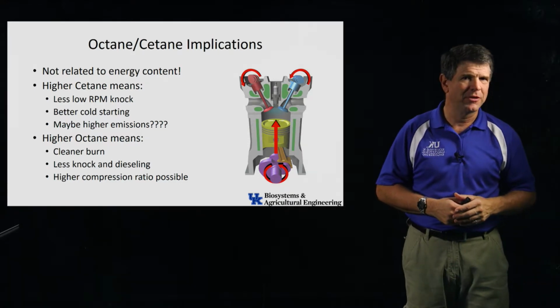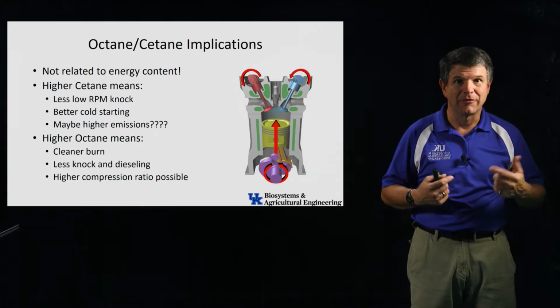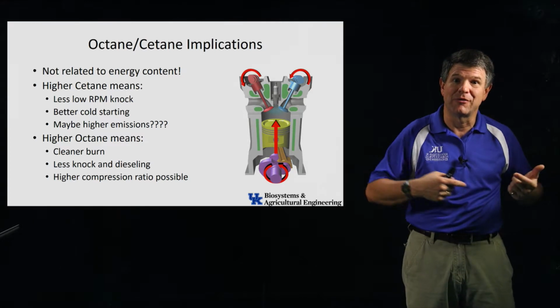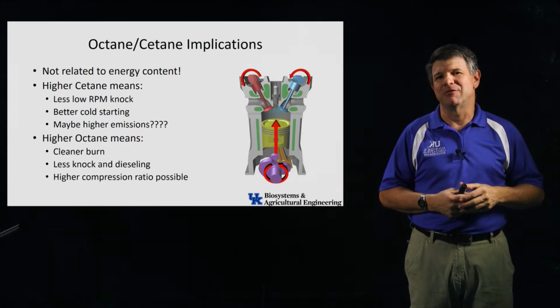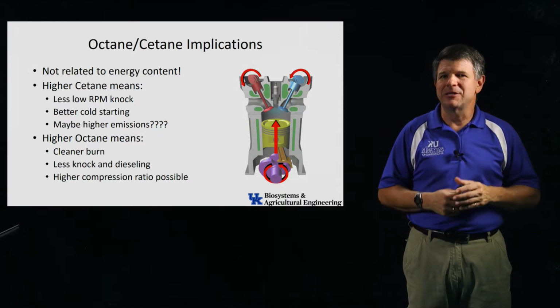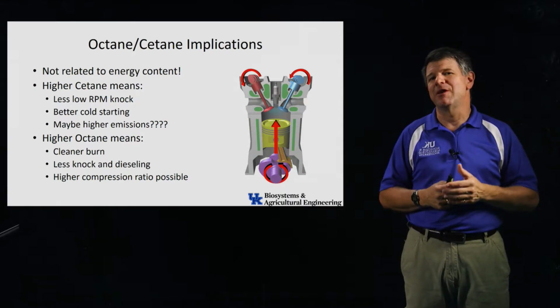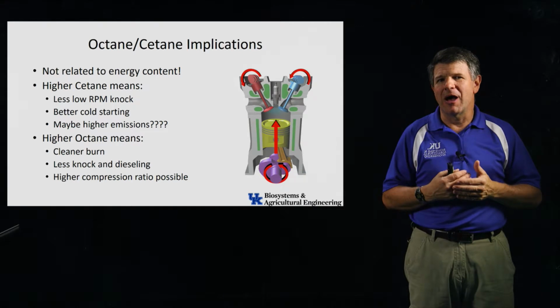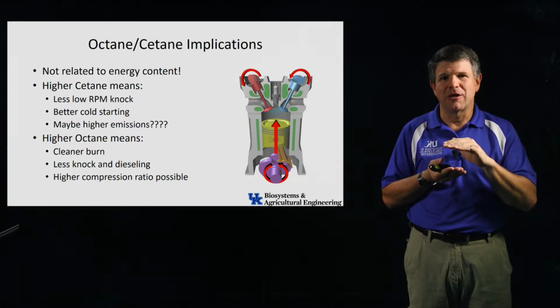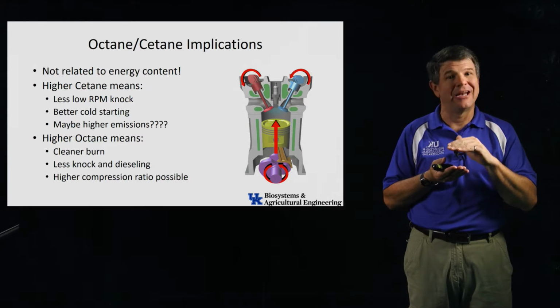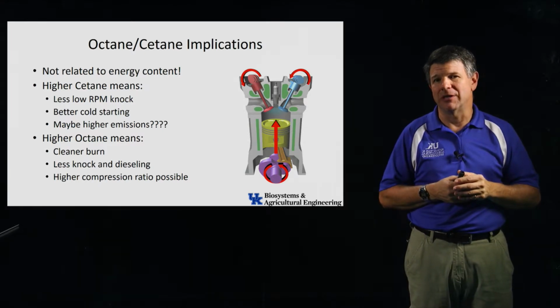Do you really have to put that really expensive fuel in your car? I wonder if it's a conspiracy between that auto manufacturer and the fuel companies that like to sell that expensive fuel. Yes and no. There's some difference. So here's the bottom line. If your engine will run on low octane fuel, run it on low octane fuel. You're probably not going to get any advantage from a high octane fuel in that engine.